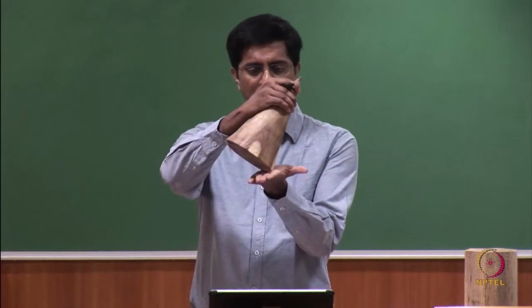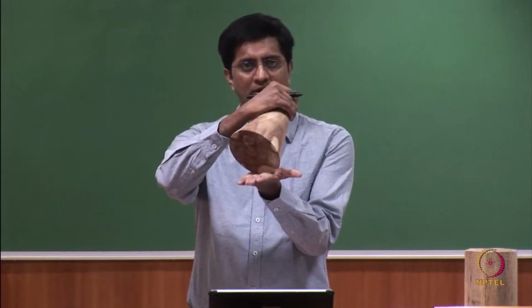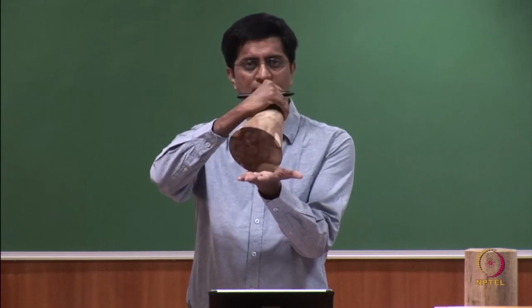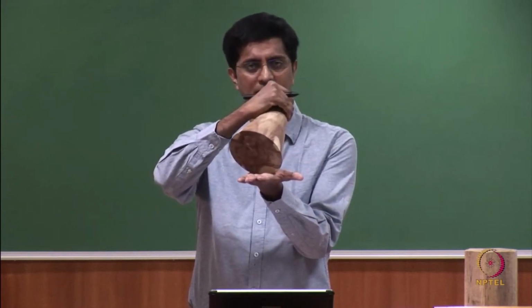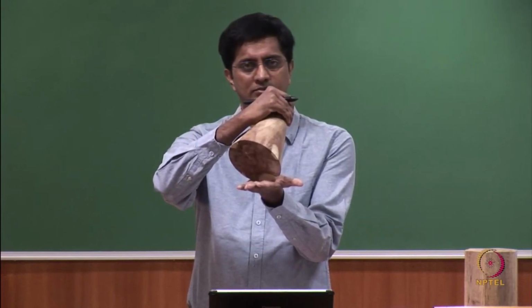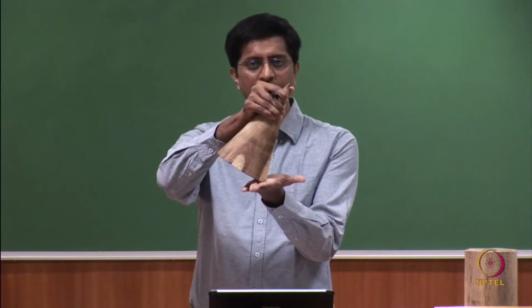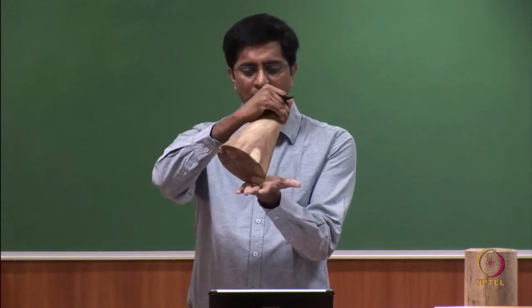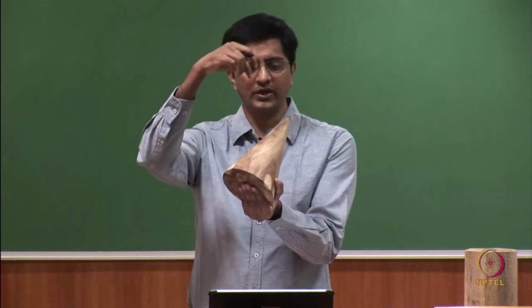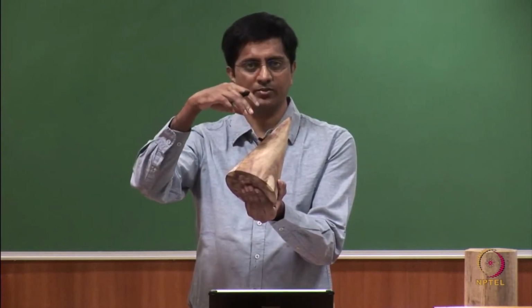Now, coming to the last view, where the axis is now inclined to the vertical plane. So, before rotation and after rotation, which shape will retain the same? Where will you have the true shape? Will it be in the front view or the top view? If you follow it clearly, you will notice that the top view will retain the same shape.